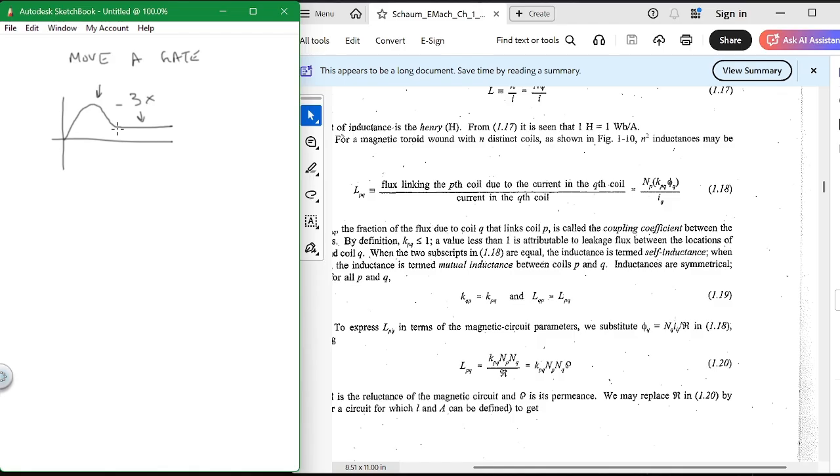Now, what does that mean? Well, if you size your wire to this, it might work, but you have to start it with this. So you have to size your wire to the starting current. It'll never work if you don't get over that hump. Does that make sense?